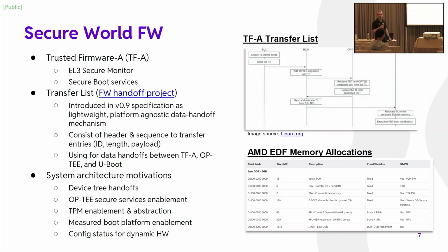But we're really excited about what Transfer List is going to bring in and that firmware handoff capability in terms of being able to build that Lego block example with the secure OS. And as a system architect, my motivations with this are really around device tree handoffs, being able to implement and start to stand up some of these hardware-specific OP-TEE secure services like the TPM, like the boot NOR flash and getting that off.